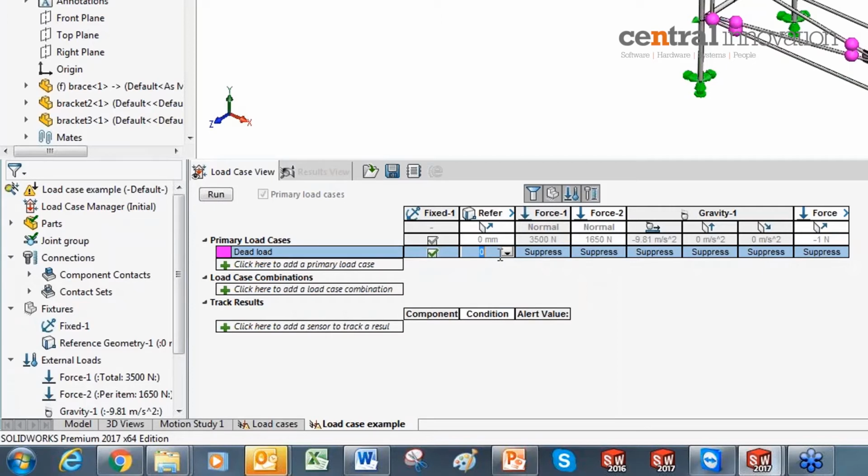It is constrained after 2 mm, or it is limited to move only up to 2 mm. So in that case, I want to test it for that condition, the 2 mm limit. So I can give 2 mm in here. I can choose to change the values, and I can test for different loading scenarios, different fixture scenarios. But I'm not going to change that. I'll keep that reference geometry as 2, but you have the freedom to change that value.